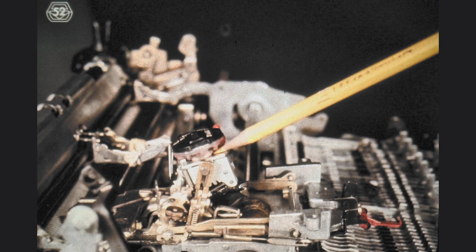Should you ever come across a broken element that still has its center socket, or hub, intact, it is a good idea to grind off all of the characters until the only thing left is what you see on top of the tilt ring in this picture. A partially ground off element like this one lets us check the clearance that exists between the tilt ring spacer and the hub of the type element, as indicated by the yellow pencil. We must make very sure there is no physical contact of any kind between the hub of the element and the tilt ring spacer, and we need to check it all the way around the tilt ring.